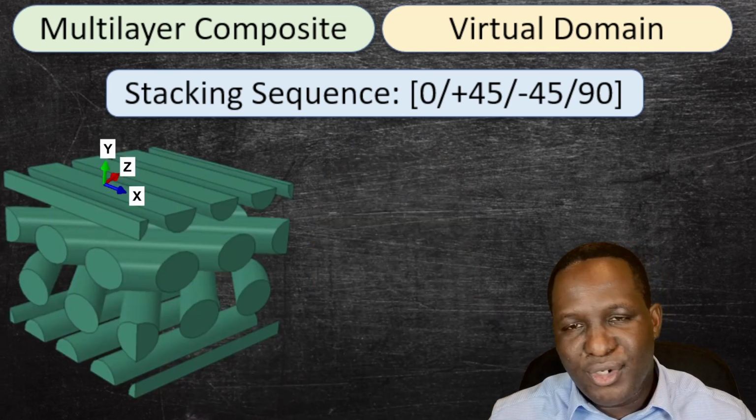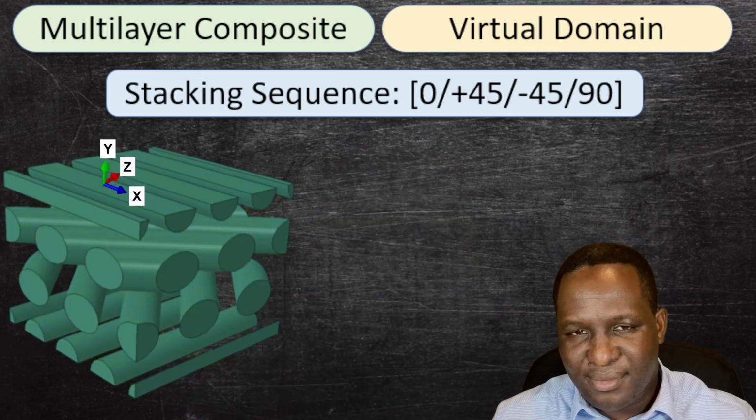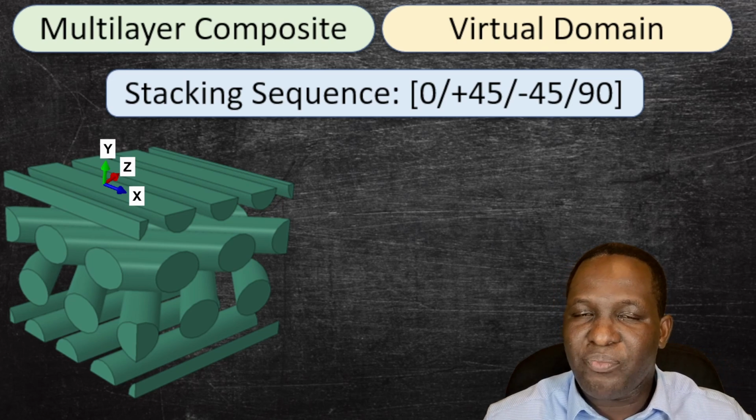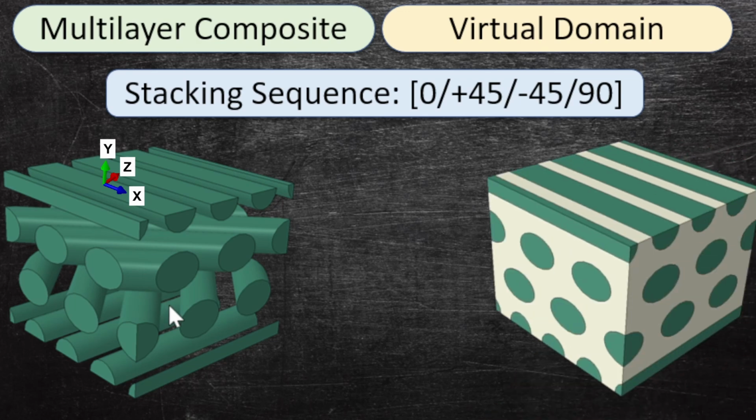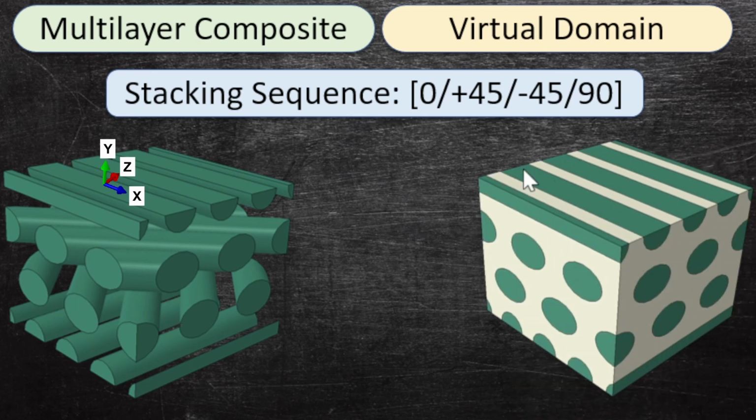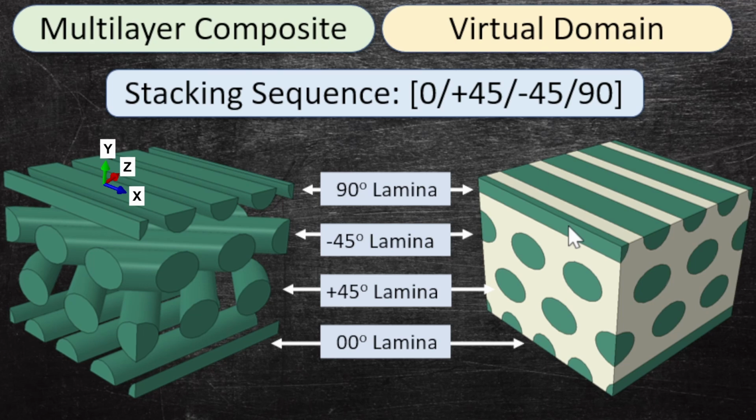So to look more closely at that, the stacking sequence has been defined, and that's really depending on the orientation of the different lamina of the material. So here we've shown different fiber arrangements, and when you mix it together with the matrix, you get this arrangement. And just by way of associating each lamina to the fiber orientation, we've got the 0 degrees at the base here, a plus 45 degree here, and that's minus 45 degree here, and a 90-degree orientation. So this is with respect to the main fiber axis, which is a 0 degree direction.